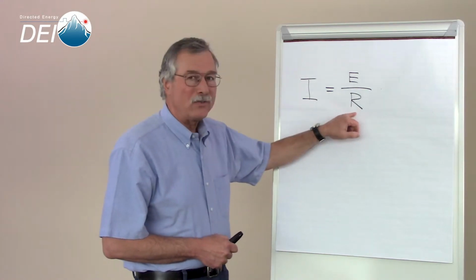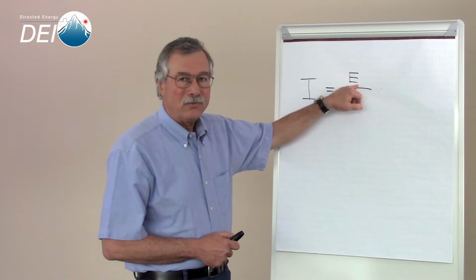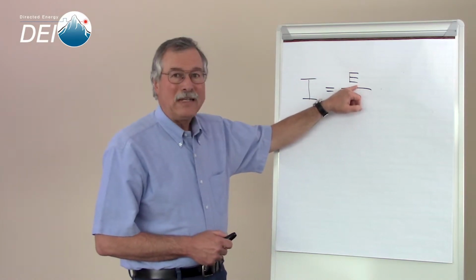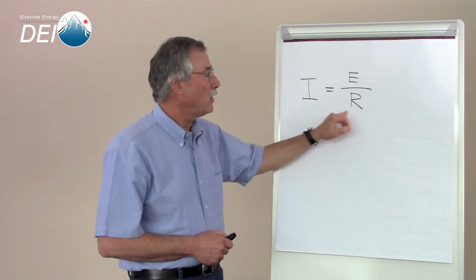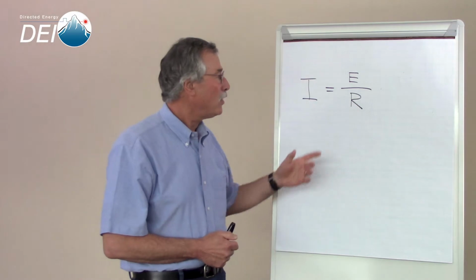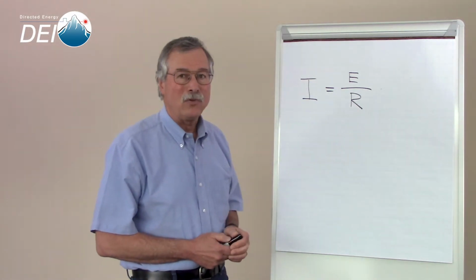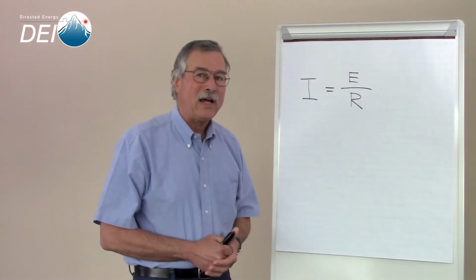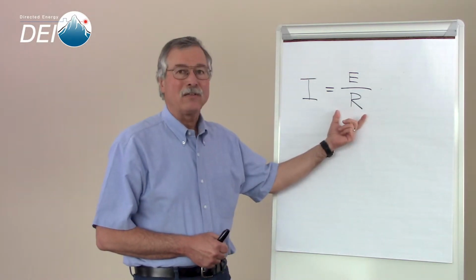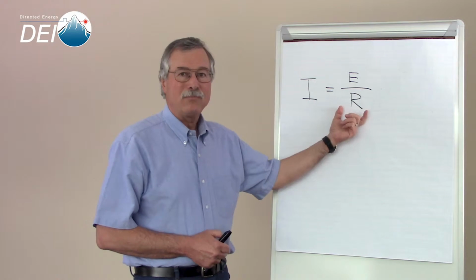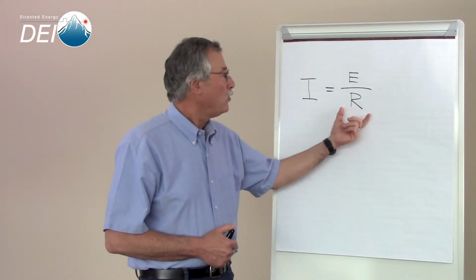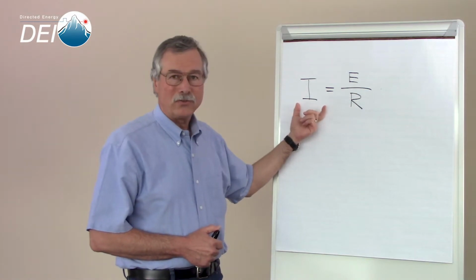and we've picked the resistance, we need a voltage to force that current. The amount of voltage that we need to force a given current through a given resistance can be referred to as compliance voltage. And the important thing is that we have sufficient compliance voltage. When you pick a laser diode from a catalog, you are picking the resistance in effect. That part has been set by the manufacturer and the characteristics of that laser diode. You can also decide how much current to force through the laser diode.